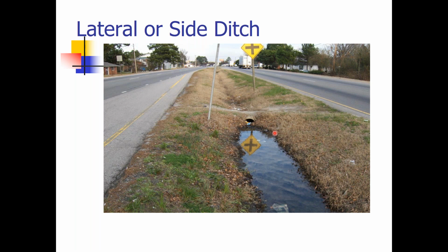Clogged culvert, culvert too high, plugged tile. Invert should be lower. Looks like pipe is blocked. The cross drain is too high. Pipe is too high. Trash and debris. Culvert needs repair. Needs maintenance. Blocked inlet. Standing water only one side of the culvert. Crushed culvert. Inlets blocked by rubbish. Water looks stagnant. Pipe clogged. Pipe blocked. Culvert clogged. Pipe needs to be lowered.